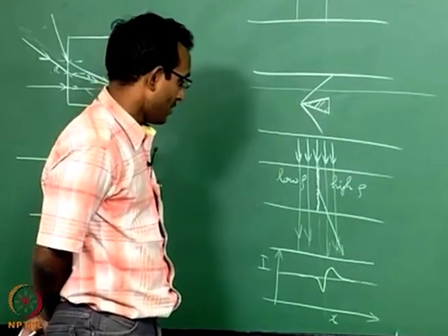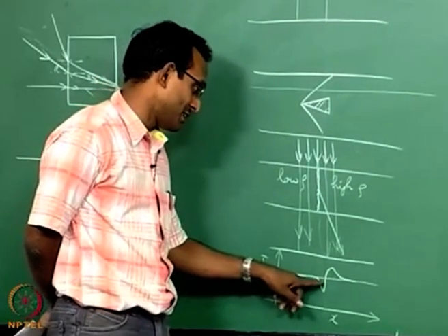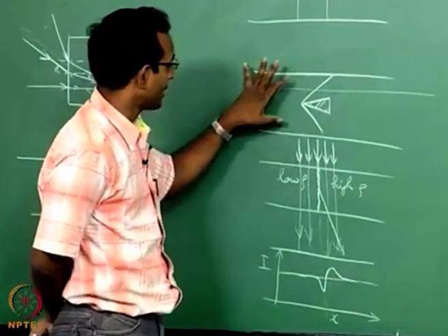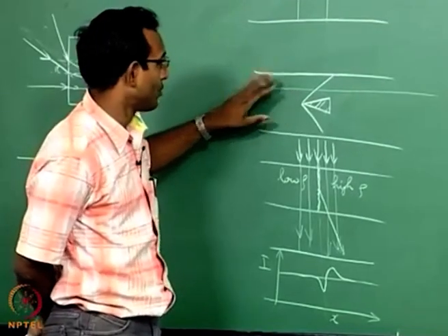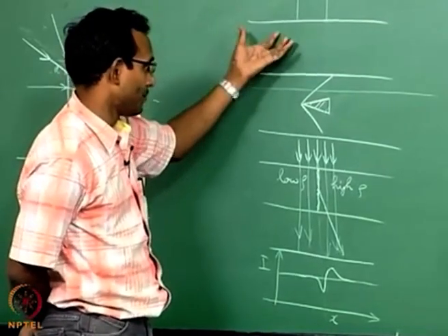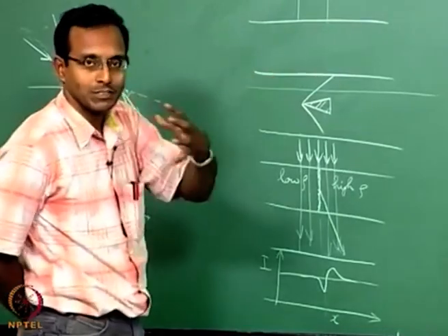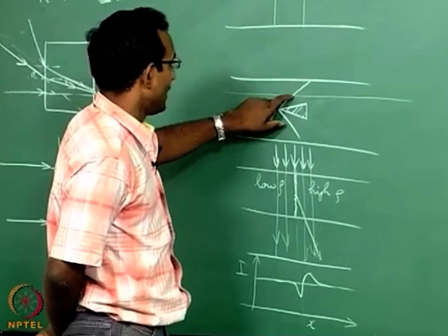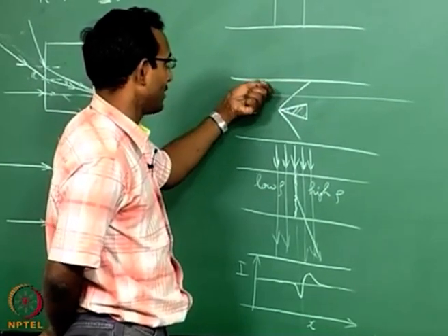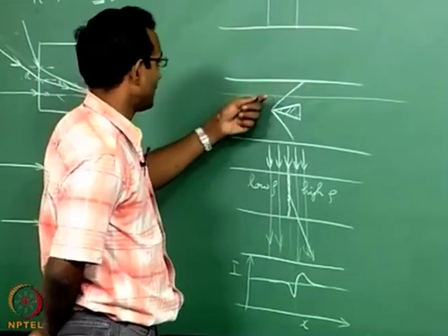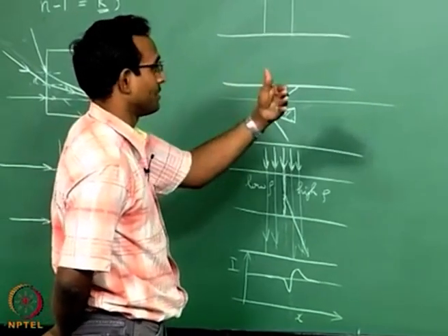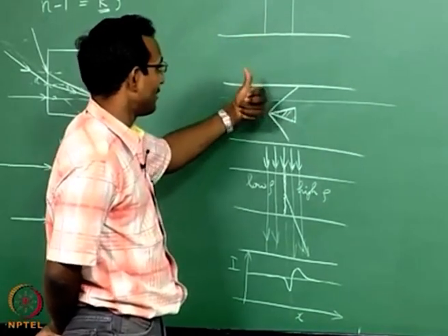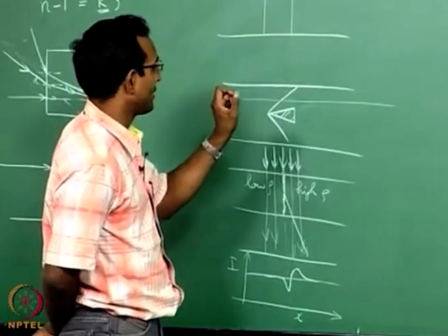Okay. Now, what does this mean when I have intensity low, intensity high? When I look from this side, this is my side view, I am again going back to side view. What did we talk about? We said light is coming from behind the board to this way towards us, and I am saying at that location there is light coming very close to the shock, deflecting to downstream direction. That is what has happened. So, instead of coming here, it has now gone somewhere else. Say I put a screen somewhere this far, then I am going to see that the light is deflected so much. So, this region will be dark and the next region will be bright.